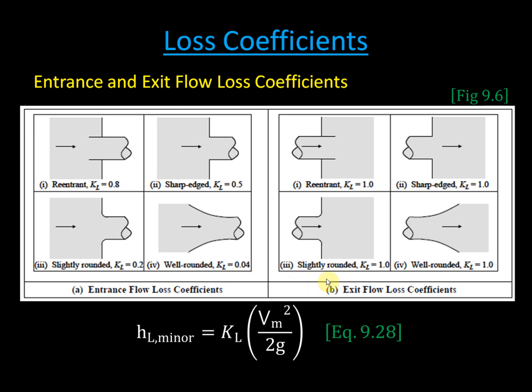Now compare that to exit flow loss coefficient. Something important on this exit flow loss coefficient is that it has to be flowing into a full container. If it's not flowing into a container, into another liquid, into itself, it's just like a free jet, so I don't have any loss coefficient.